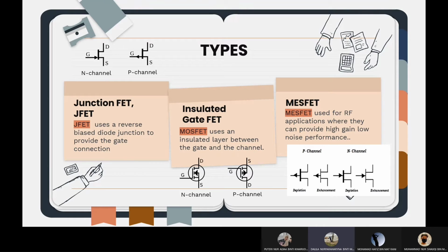The second type is MOSFET. MOSFETs are widely used in many areas of electronics and particularly within integrated circuits. The key factor of the MOSFET is the exceedingly high impedance these FETs are able to provide. That said, there will be an associated capacitance, and this will reduce the input impedance as the frequency increases.